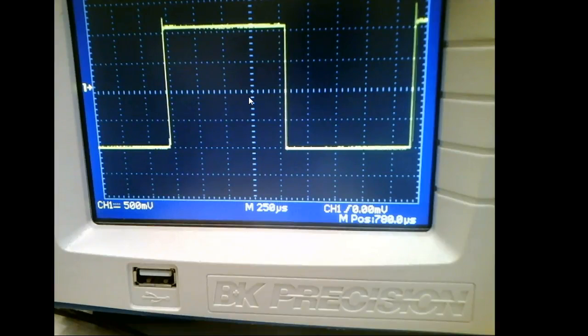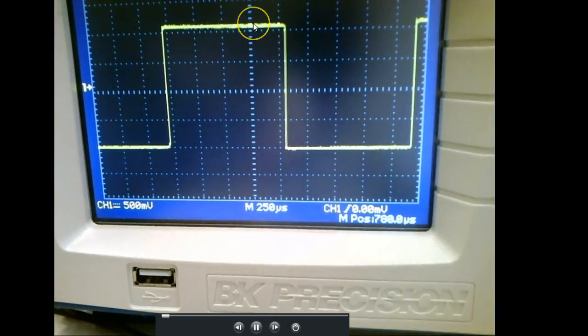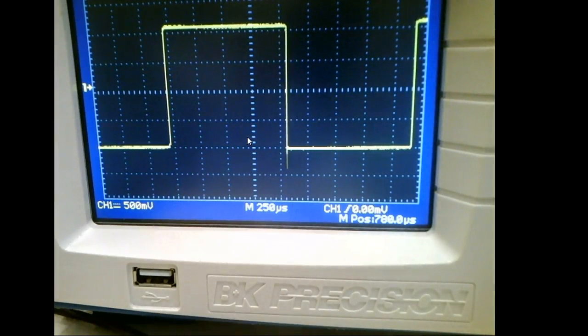So are y'all okay on that? So you said it's a 0.1 class right there in between the lines? It's on one division. Yeah, each one of these. If this is 500 millivolts, that means each one of these should be worth 100 millivolts, and that's what I would look at. What I do when I measure on a scope, I've been using these so long, I don't multiply in my head. I count.